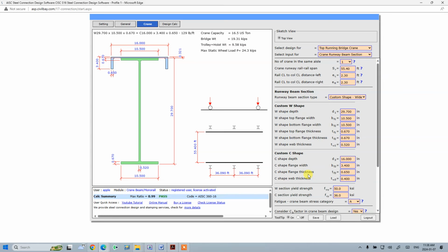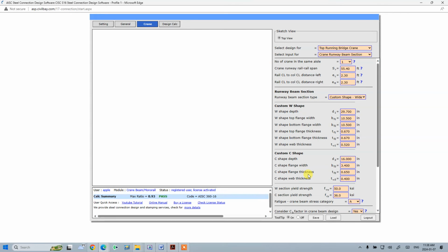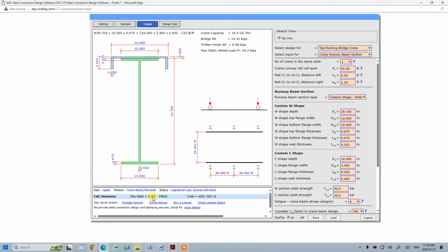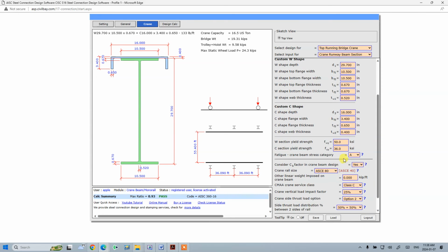All right. So we now use the build up sections, get 0.93, okay? And make sure your steel yield strength is right, because sometimes the build-up plate has lower yield strength. But we assume the same for comparison. And I think for build-up, if everything is built up, these two will be the same value.